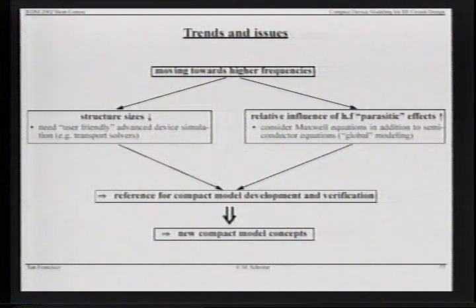Now, when we look at this in terms of compact modeling, then we're wondering, of course, if we get 20 nanometer base widths in a bipolar transistor or 60 nanometer MOS transistors, whether our present compact models and the model formulations, which most of them rely on drift diffusion, are still correct. There's just very few models, maybe exploratory models, that use a wider scope in their equations.